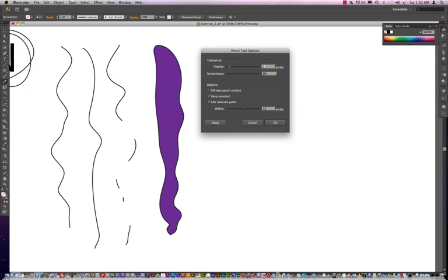Now if you knew that you wanted to apply some watercolor type effects to that line work afterwards and you didn't want to have too many sharp jagged edges, you'd probably choose a smoothness amount higher because it will result in a smoother path. And the opposite of a lower tolerance, it would create more irregularities and preserve them. So the preset value is for the smoothness to be set to 0 because it assumes that you want to put in quite a lot of detail when you're drawing.